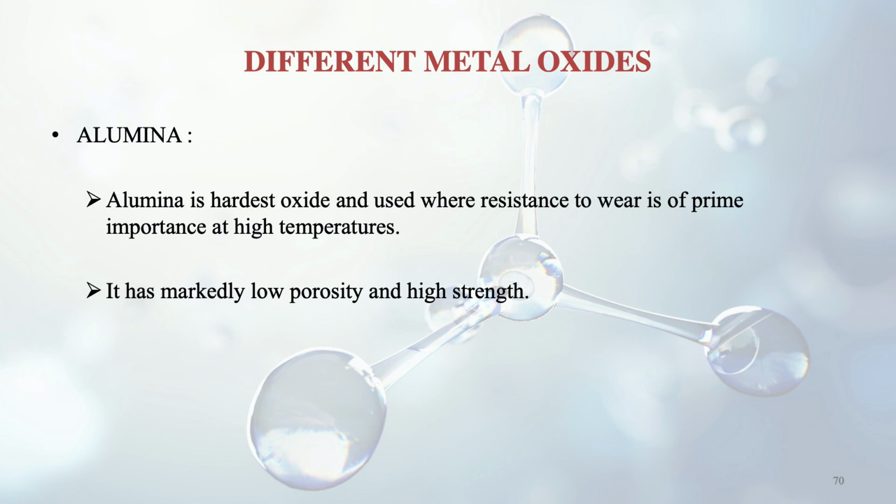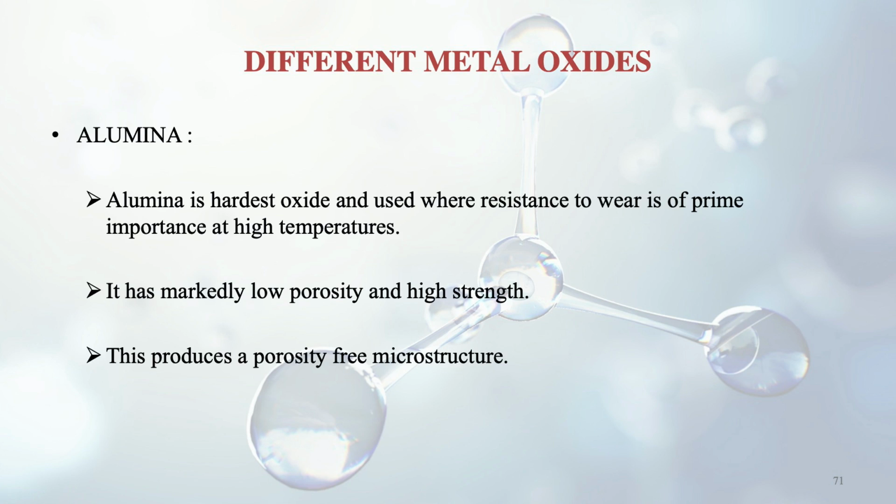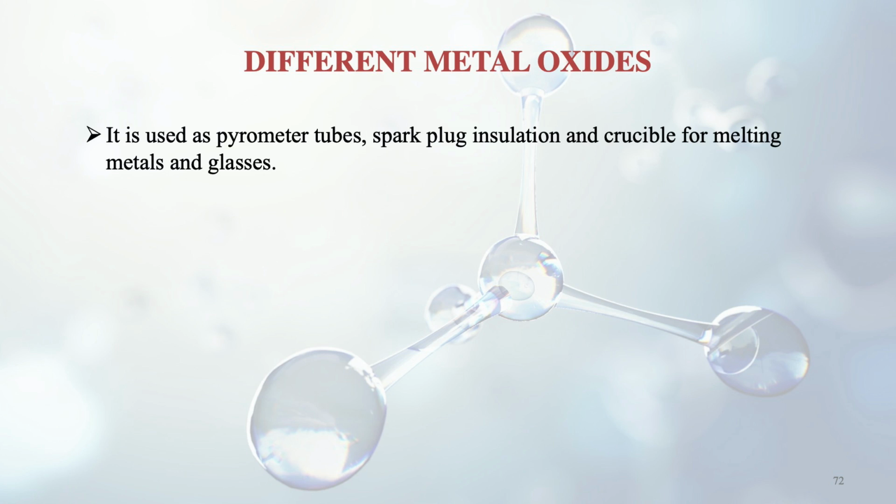It also has markedly low porosity and very high strength. As soon as it has low porosity, the microstructure will be free of pores and it will thus lead to higher strength. Its applications: it is used in pyrometer tubes and spark plug insulation and crucibles for melting metals and glasses.